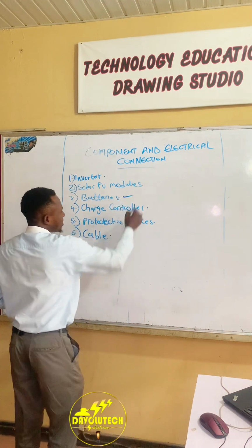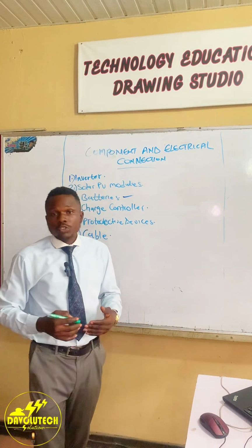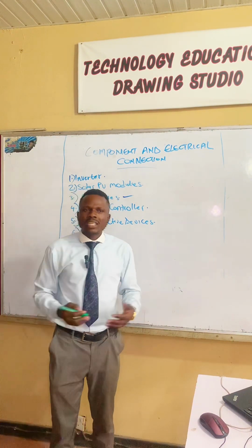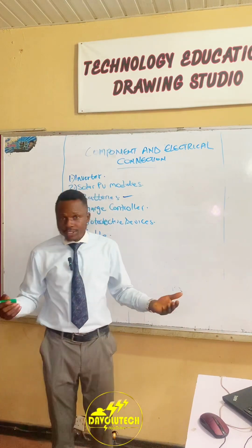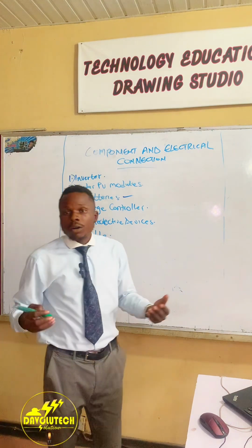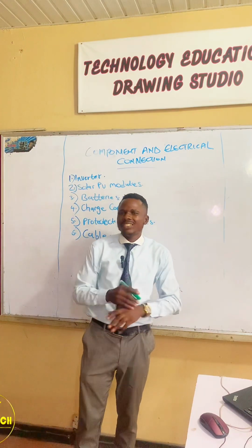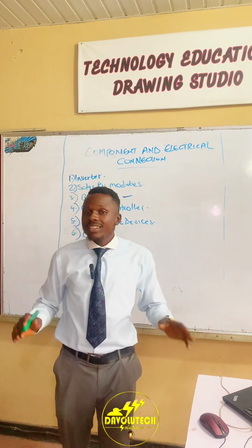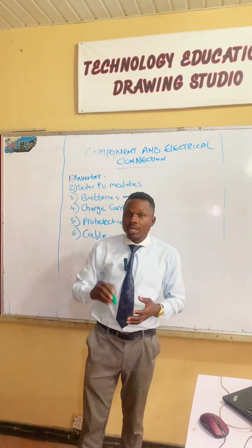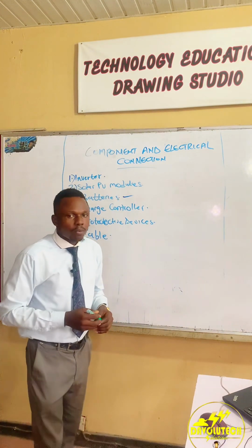And of course, we have our battery, which serves as a storage bank. That is the purpose of your battery. A battery is used to store energy that your PV has harnessed from the sun, or energy from using an inverter to charge your battery, for later use. It comes in different types: lithium-ion batteries, lead acid batteries, and tubular batteries, depending on their chemistry. They also come in various nominal voltages; the common ones are 12 volts, 24 volts, and 48 volts, depending on the manufacturer.